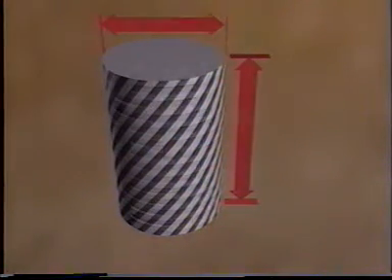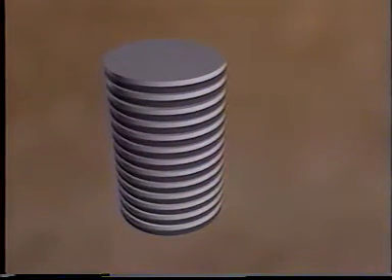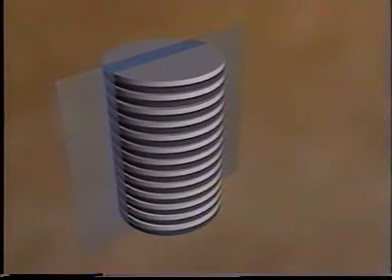To understand why, we can imagine that the shaft consists of an infinite number of infinitely thin discs. When the ends of this pack of discs are twisted, each disc slips a very small amount with respect to its neighboring discs. But the diameter of each disc does not change, nor is there any force to change the length. As the torsional stress increases, the slippage and deformation continues. Eventually, fracture will occur on one of the transverse shear planes. This plane is essentially the interface between two adjacent discs.